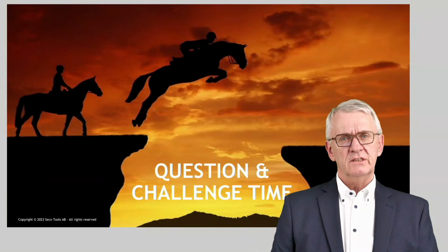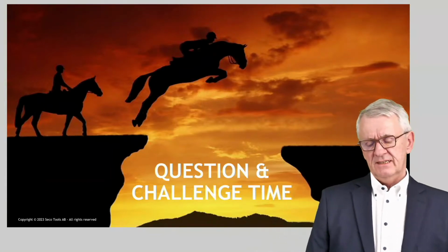I would even say the question itself should not be a question. It's the chip thickness that is determinative for the power of the operation. It's not the feed.